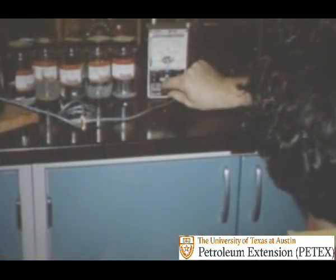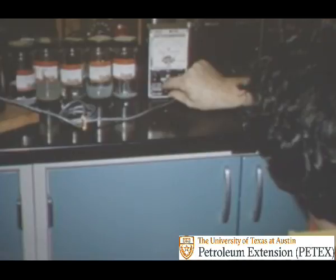To check the activity of the mud, that is, to see if water is being transferred from a formation to the mud or from the mud to a formation, the relative humidity of the mud is measured with an electrohygrometer. If water transfer is occurring, additions can be made to the mud to stop the problem.